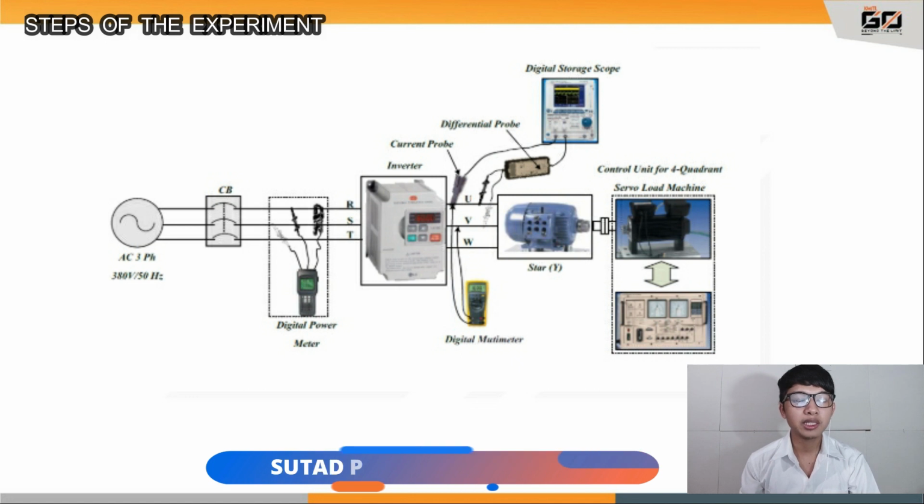Now, let's have a look at this picture. The step 4 experiment. The induction motor is driven by the inverter to test the operation of the magnetic field and constant torque, from measuring voltage, current, motor speed, and power at the frequency range 1 to 100 Hz by the devices and measurements as shown in the picture.